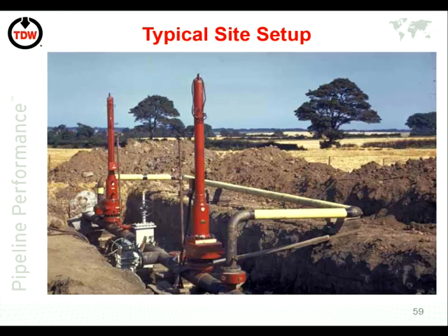And we've also put 2 extra fittings on either side of that. We've put a bypass around there. So that work site is ready to be worked on. So this area here will probably be depressurized now, so the contractor who has come in can work on that. Well, the end operator who's taking the gas, let's say it's a power station or something like that, is still getting gas because it's coming around the bypass instead of coming through the main pipeline.